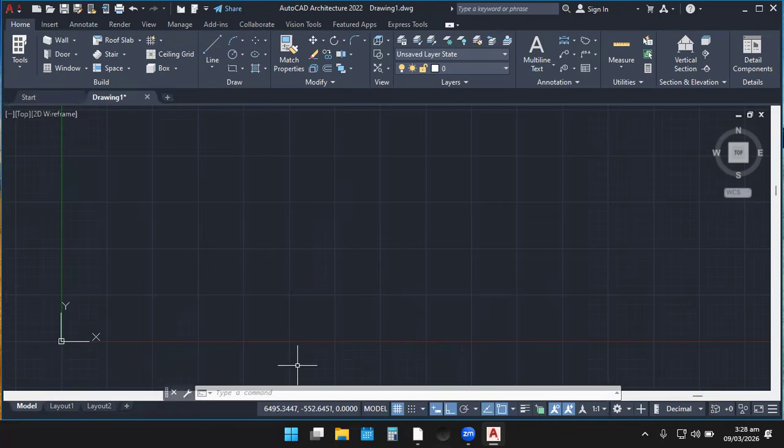So even before we continue, let's set our snap to 10 units and our grid to 100 units. Okay, if you are looking for that, you can come to the control command and we type the snap over there. We choose it over here, and then that menu will be displayed. We can choose to enter it manually, or we use the command also. So let's escape this. You press escape on the keyboard, then it is gone.